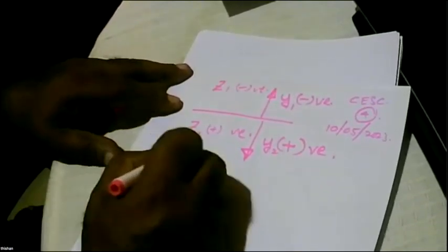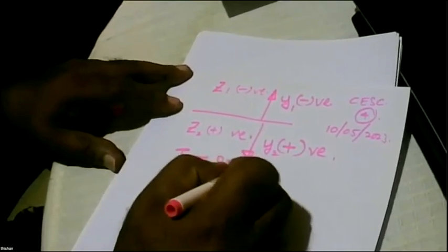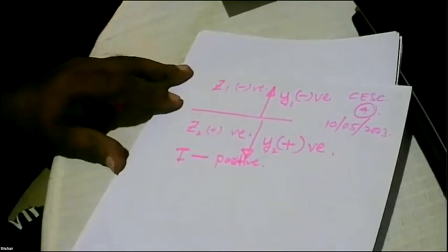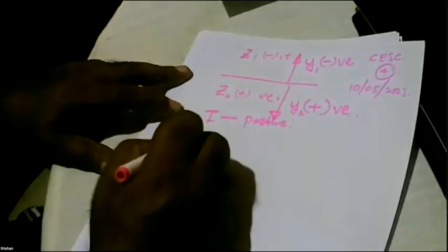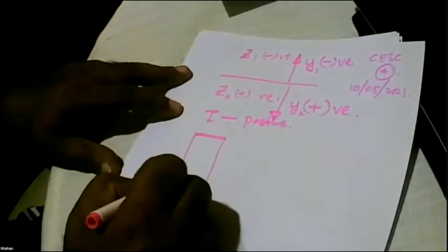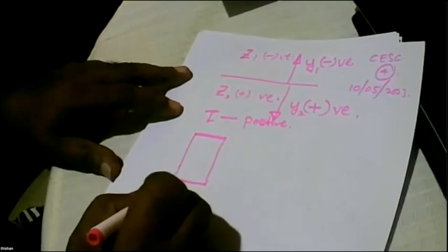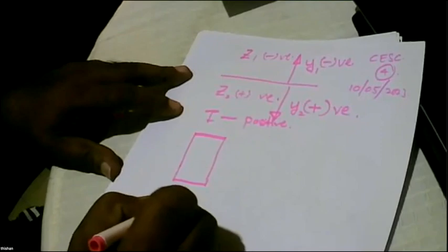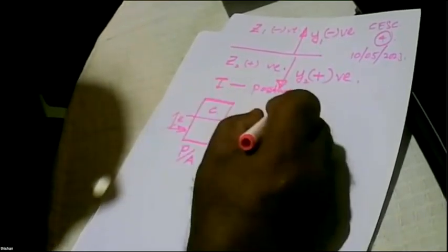I value positive. I is the second moment of area. It cannot be negative and positive. It's always positive. Right. Now we take the section again as earlier and apply a prestressing force, and compression is positive. So you get P0 over A. And because the tendon is not at the center, with an eccentricity, this is compression.